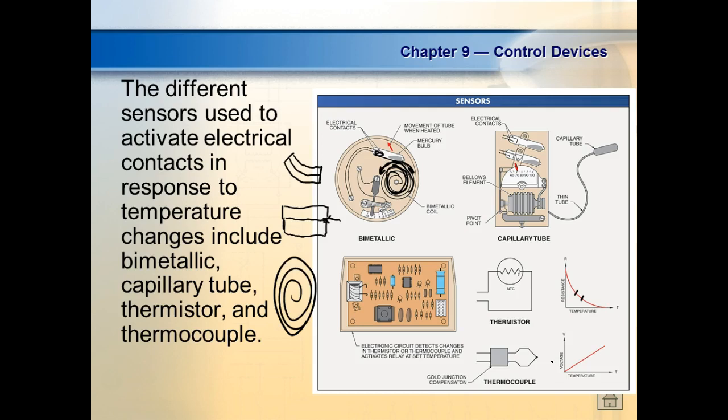What ranges do y'all use to keep your house at? So what's the coldest you let it get? Yeah, 60 and 72. So that's only a 12 degree range. So since we're using it on a very limited range, the thermocouples work out really well, and they're pretty cheap too. So this is my old digital thermostat.